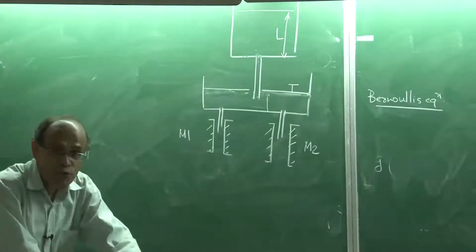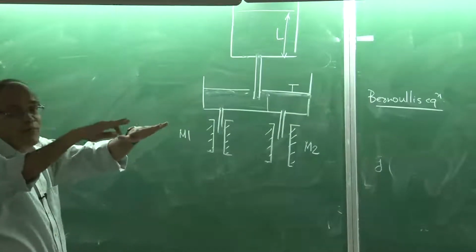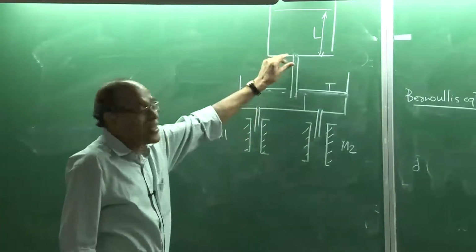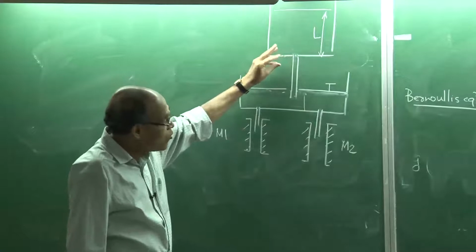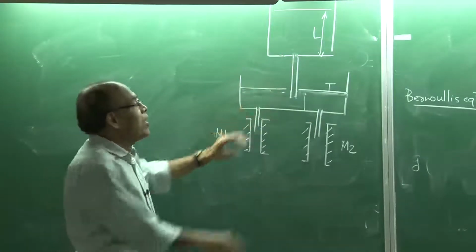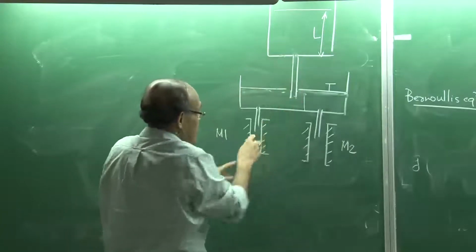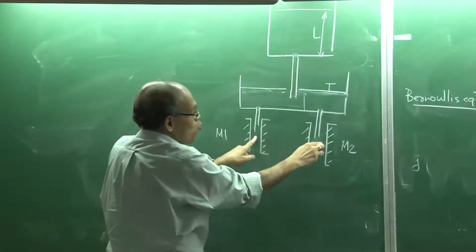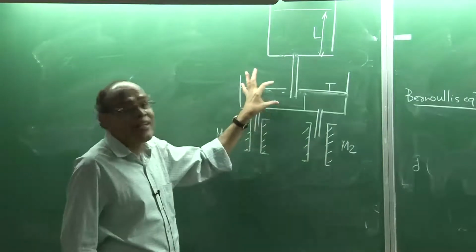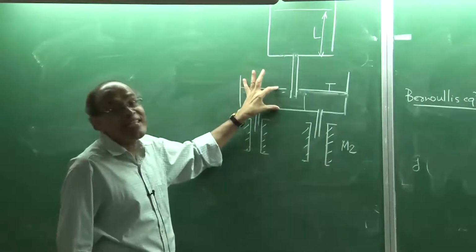Initially, we fill in the tundish, and then after some time we match the inflow rate and the outflow rate, and there are valves there, of course. Through the valve I should be able to regulate the flow, and I match, and then I get a constant bath depth. If the rate of inflow is equal to the sum of the rates of outflow through the two molds, I can say that the level will be constant, and that is the steady state period of operation of the tundish.